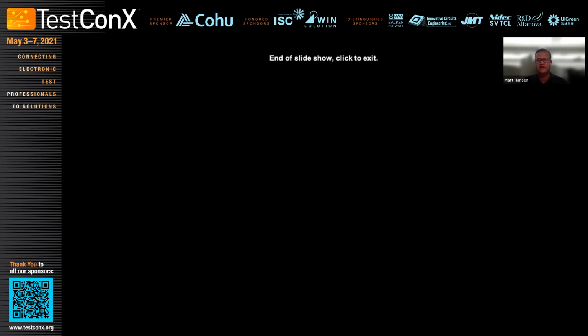I think a lot depends on power density, how much current you are flowing through a single pin. So current carrying capacity, of course, comes into play. The environment, the cleanliness of the floor, the cleanliness of the package. So that's a very hard question to answer, which is why I think most vendors rely on mechanical insertion data, which is mostly static, right? In our case, we're getting hundreds of thousands on elastomers in general, but depending on the application, a 2 amp pin versus a 1 amp pin would be a very different outcome, right?